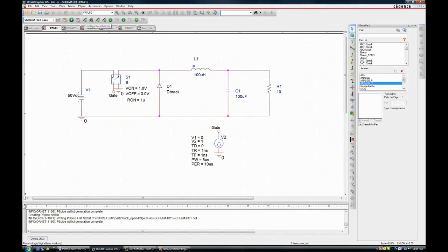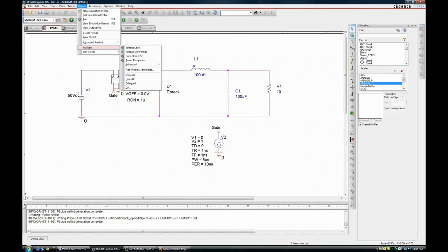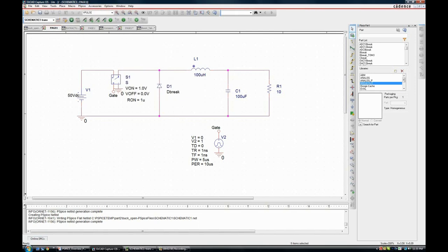Let's talk about our markers. We've got voltage markers, the differential voltage marker, current into the node marker, a power dissipation marker, and if you look, there is this marker window under PSpice, which provides you some more advanced markers, which really are mostly useful in the AC analysis end of things. So when we do AC analysis and we want to see magnitude of a signal in dB or phase of a current in degrees, or phase of voltage in degrees for that matter, we'll select that there, but we'll save that for then. Anyway, for right now, let's pick voltage of the output.